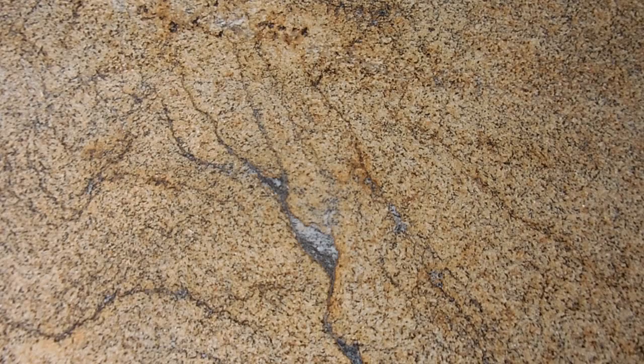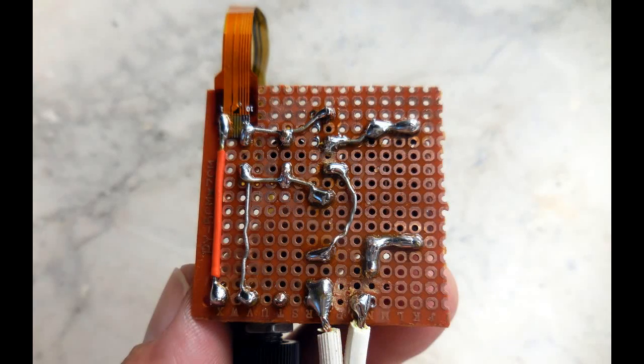Now what I'm going to do is show you a couple of close-up images of my circuit inside that plastic project box. In this image here, you're looking at the back side of my circuit board. At the very bottom, you can see where the white AC line is coming in, and I scraped away all the copper between those two terminals to ensure there's a wide enough space that there will not be any shorting out between the hot and the neutral wire.